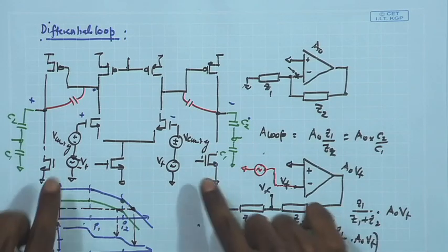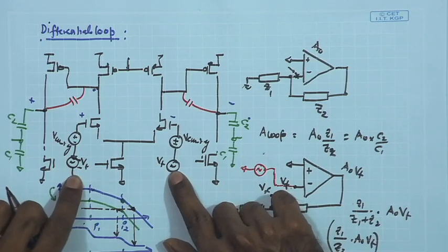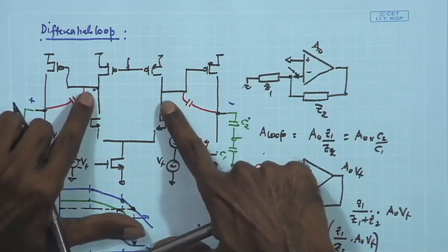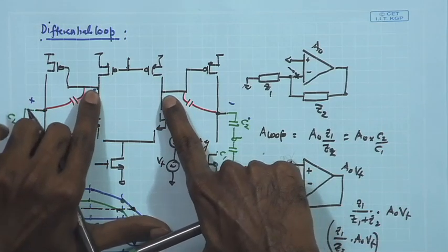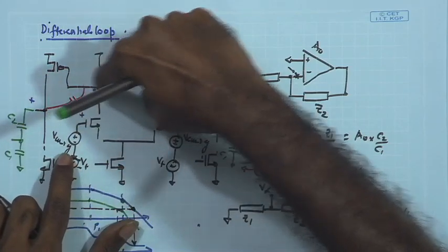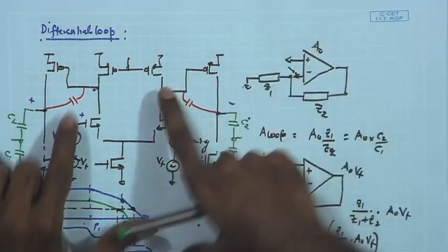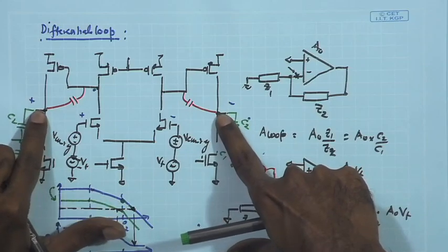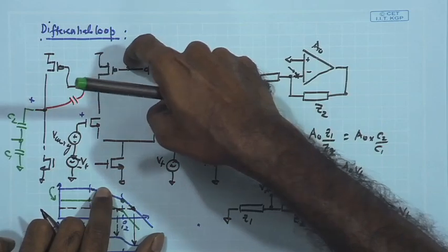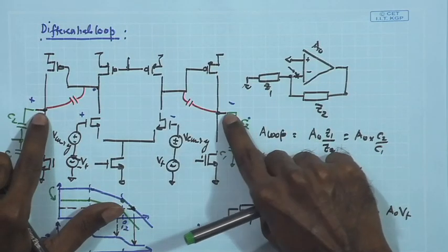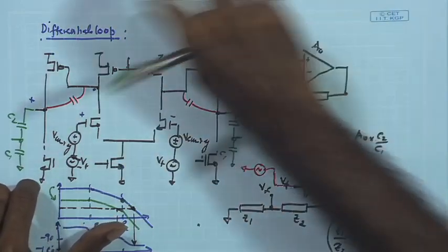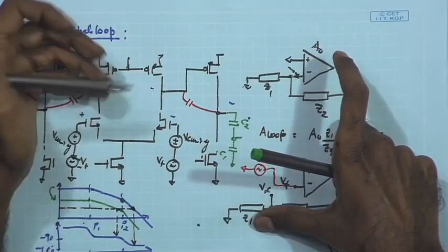If the test signal that you are applying at the input is fully differential, the output signal over here is not going to have any significant common mode, therefore common mode signal is anyway 0. If you have the common mode loop, you know that the output DC potential over here is also going to the common mode error amplifier, and its feedback will be coming at this point. And since ideally there is no common mode signal at this point, that loop is not going to have any signal coming over here.